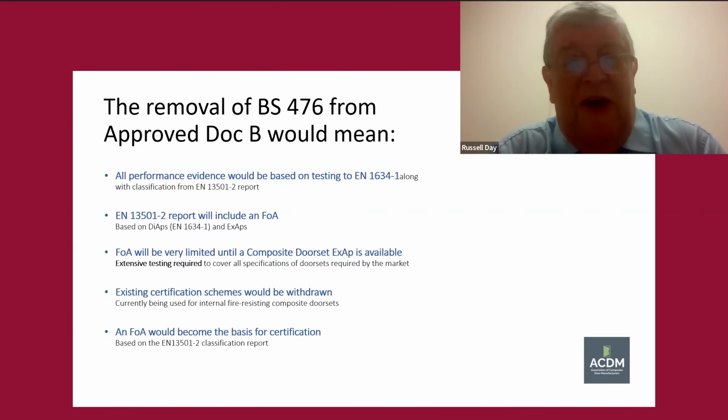So we will reduce the scope of use of internal fire doors simply because we're withdrawing what is a field of application developed by fire engineers. The field of application will be very limited for composite doors. Timber door sets obviously have a full XAP available. So once the testing's done and a classification report is produced, the XAPs there will be fine in terms of giving the scopes that are needed. We will have an XAP hopefully available and published within the next 2 years.